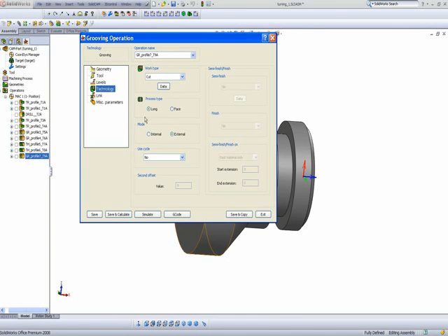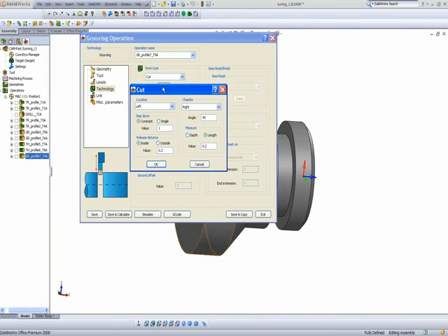In my technology, this time I'll be using my work type as cut, to cut the end off over here in my grooving operation. Now, what's important over here is the fact that I can also, if I want, add a chamfer to the corners as I'm cutting off the part. I can say I have a chamfer on the right side of 45 degrees of 0.2 millimeters.